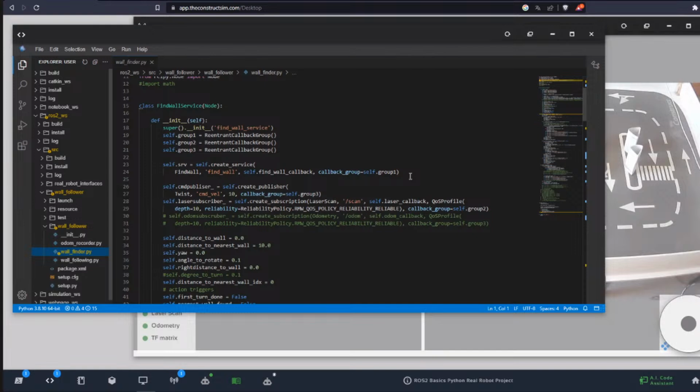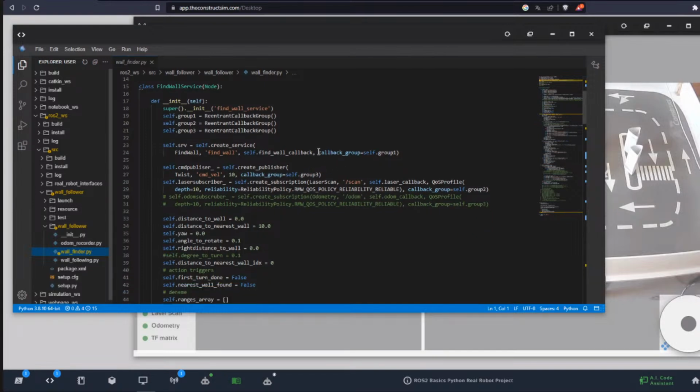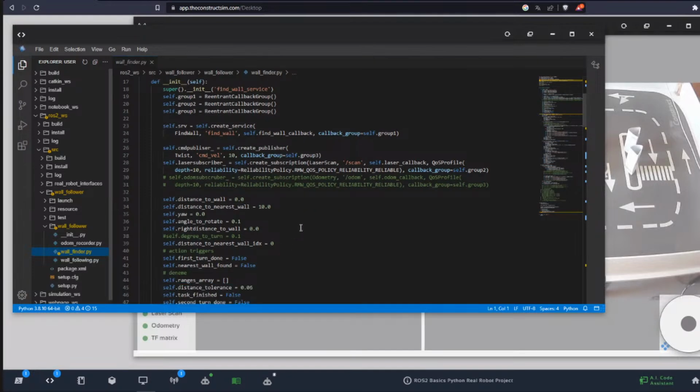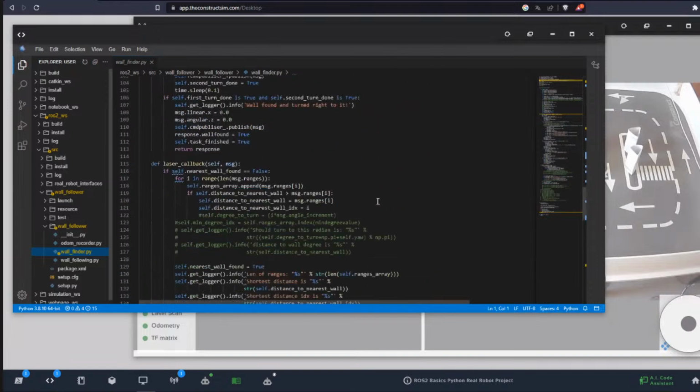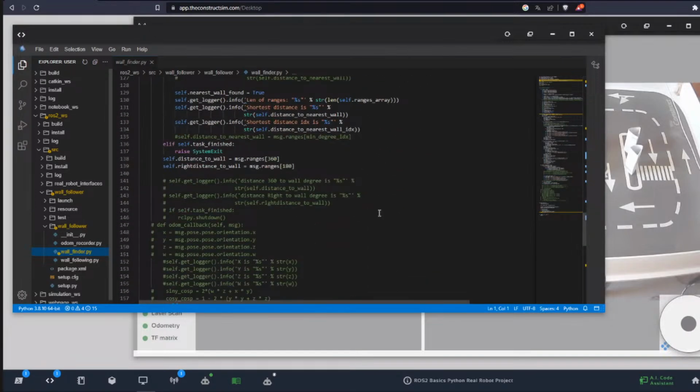Oh, actually that's interesting. Yeah. There are some global values here, and the other version for wall finding was I was calculating it with the IDX value. I would get how much the robot should rotate and then do it with the odometry. It worked fine in simulation, but in the real robot I couldn't make it work in one session, so I need to try more.